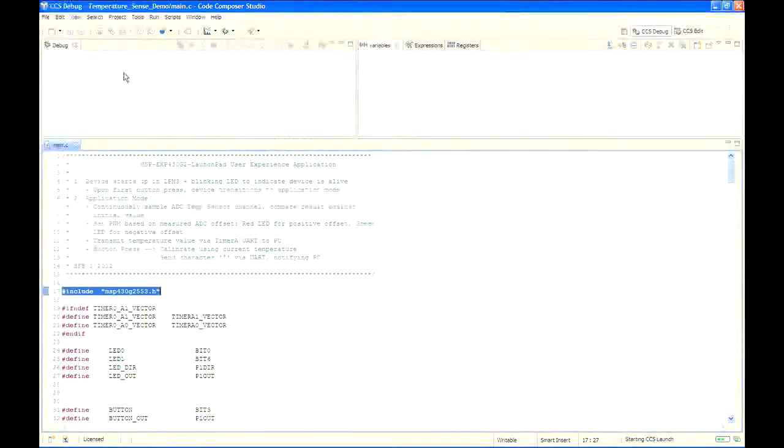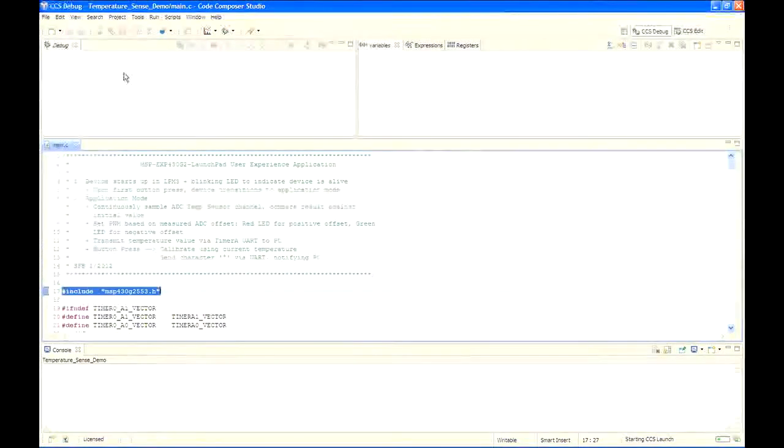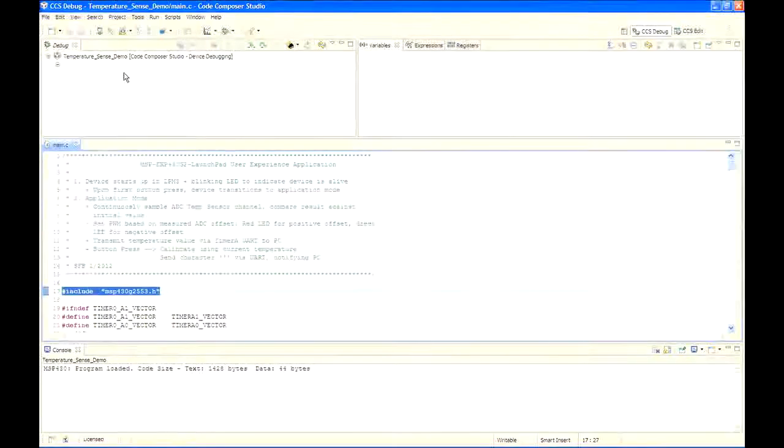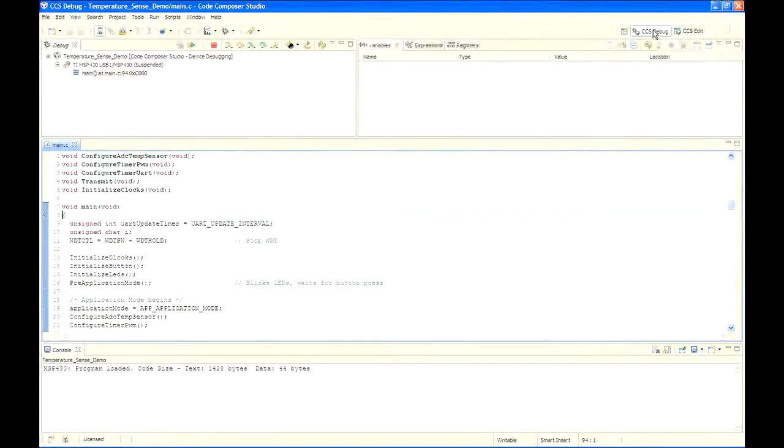After a few moments, we'll swap over to the Code Composer debug view, CCS debug. Notice the debug icon in the upper right-hand corner, rather the tab, indicating that we're now in the debug view. Click and drag the perspective tabs to the left, which we already did, so you can see all of both tabs. The program ran through the C environment initialization routine in the runtime support library and got all the way to where it stopped at the main function in main.c.